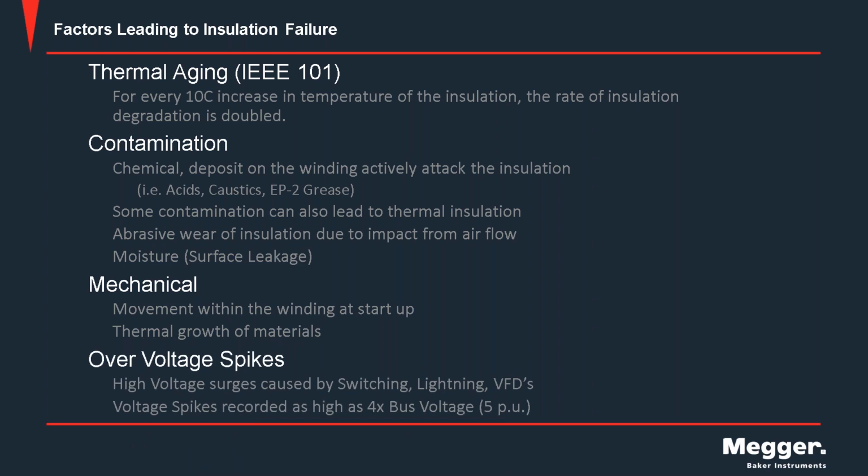And then I mentioned earlier in the presentation, the voltage spikes up to 4 times bus voltage are constantly impinging, impacting that insulation in such a way as to cause it to degrade over time. So VFDs, they switch at a rapid rate, so we're getting even higher stress from those applications that are on variable frequency drives.